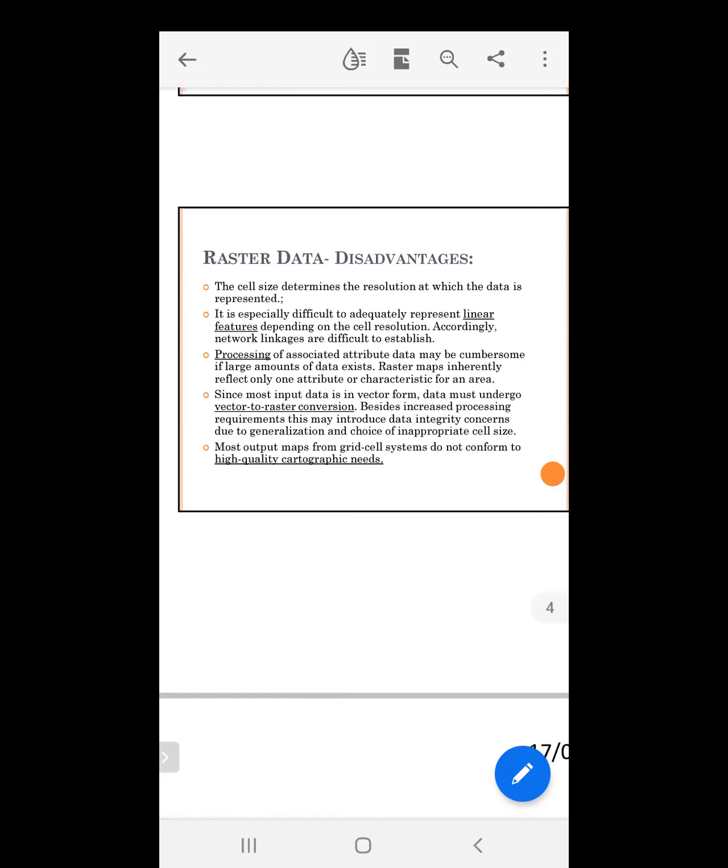In fact, far from it, because the resolution may not even help you. At 0.41 of a meter, you are in trouble right there, because the accuracy and precision required for your project is sub-centimeter, maybe 0.3 of a millimeter. We've been on projects where you have to make sure that objects are placed to millimeter accuracy, and satellite is out. Satellite images aren't going to help you, unless you use a drone with that kind of accuracy. But you need to definitely check.